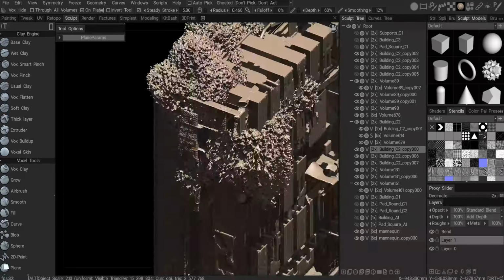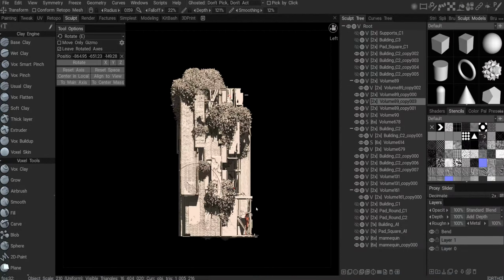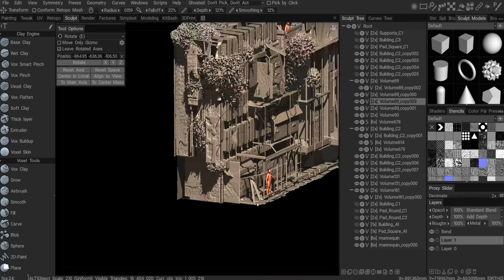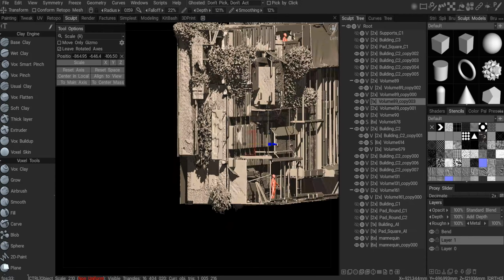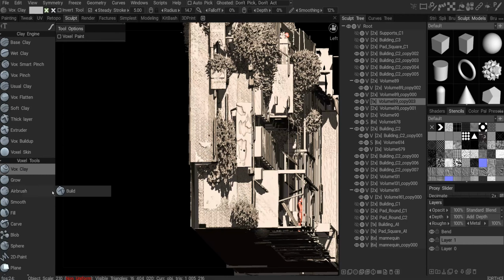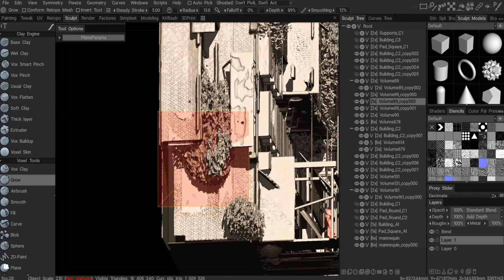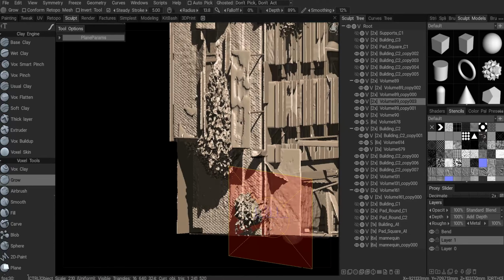You can see here the stencil went across and hit everything, including those metallic supports. I thought that looked weird and decided to modify it and use the voxel height to clean the surface. I used the voxel height on plane, so it didn't penetrate the whole thing. It only penetrated a little bit to clean the surface.